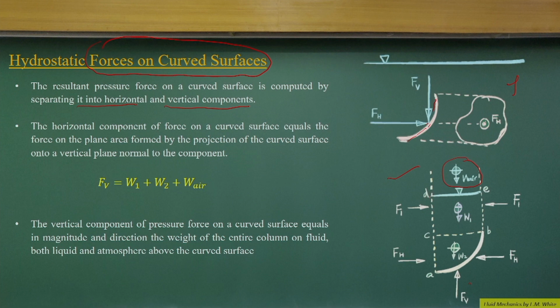Now, if I draw, this is my control volume and the pressure diagram. Okay, this is my control volume, and if I draw the pressure diagram, it will be triangular in shape. It increases linearly as we go further down in z. So we will have the pressure diagram like this. You can see that if you look at the point above the CB, the same pressure diagram on both sides represents force F1, F1 here. That means these two forces will cancel out when we take this total pressure diagram to find the force due to these pressures. So F1, F2 will cancel out, and only the trapezoidal pressure component from this point C to this point will remain.